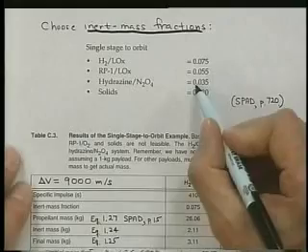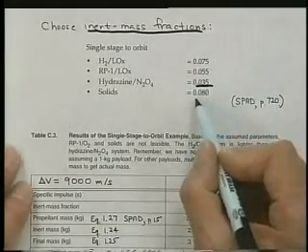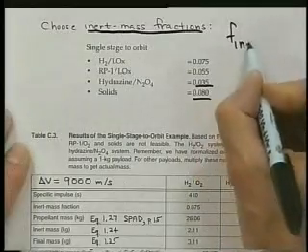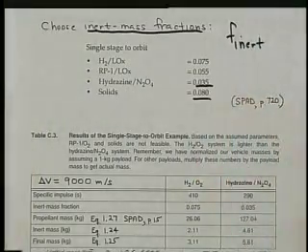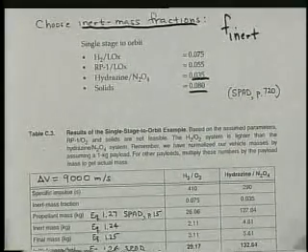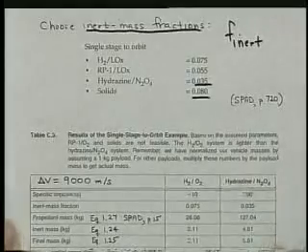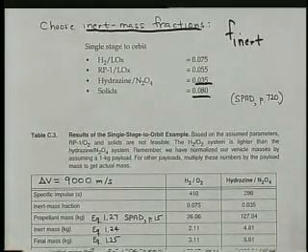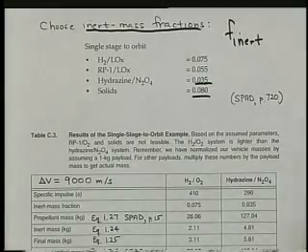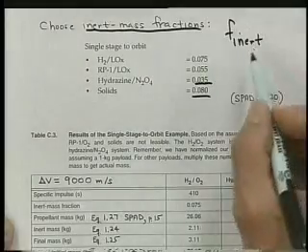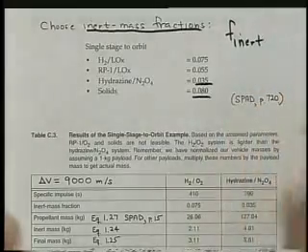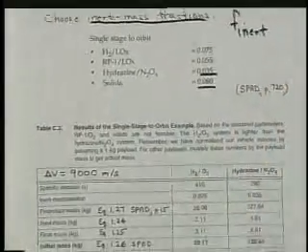We have values that range from 0.035 all the way up to 0.08 for our inert mass fraction, which again is a crucial number in designing rockets. It's how much material goes into the structure, the tanks, the nozzles, and is mass that is not propellant or payload. Everything that's not propellant or payload is part of the inert mass.